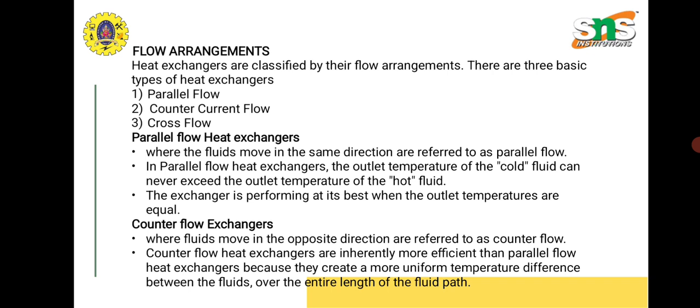Parallel flow heat exchangers: where the fluids move in the same direction are referred to as parallel flow. In parallel flow heat exchangers, the outlet temperature of the cold fluid can never exceed the outlet temperature of the hot fluid. The exchanger is performing at its best when the outlet temperatures are equal.